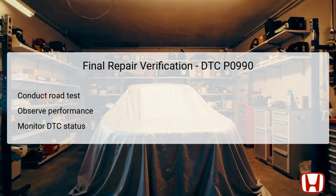After addressing the issues indicated by DTC P0990, performing a final repair verification is a crucial step to ensure the effectiveness of the repairs made. Start by conducting a thorough road test under various driving conditions to observe any related performance changes in the transmission system. During the test, pay close attention to gear shifting behaviors, particularly while engaging sixth gear.